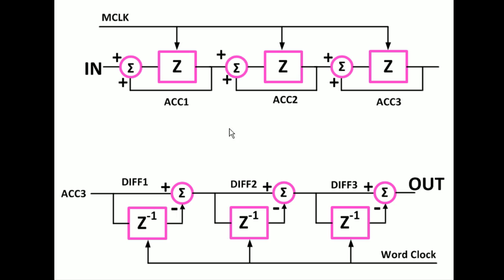And so one way to realize what we're doing is there's 2 clocks. There's 2 clock domains. There's a clock on the input and a clock on the output, because they're 2 different frequencies. One's the high frequency of all those bits streaming in. The other is the lower frequency of the final decimated value at the sample frequency that we want to end up with. So, and here's how we read this, the input signal goes through a summation and a time delay. Z is a time delay of, whatever amount, in this case 1 clock, and it feeds back some of that and gets summed in again, but also goes on to the next stage, which does the same thing, a delay in the next stage.